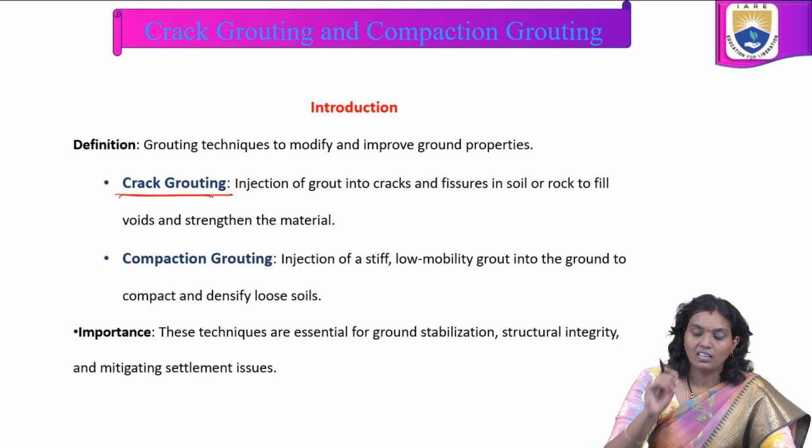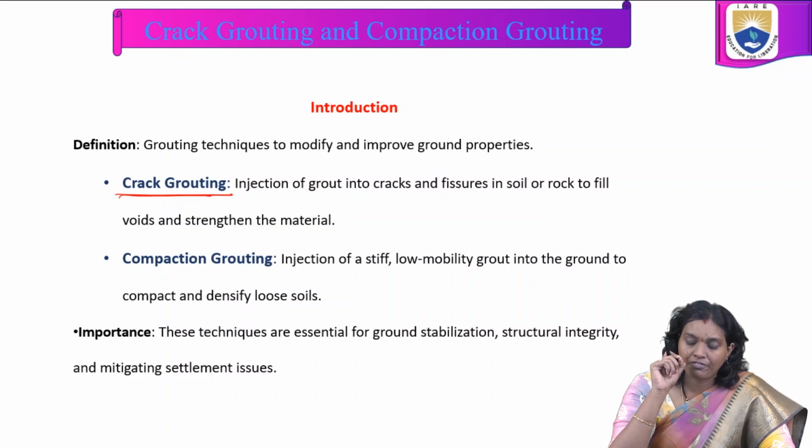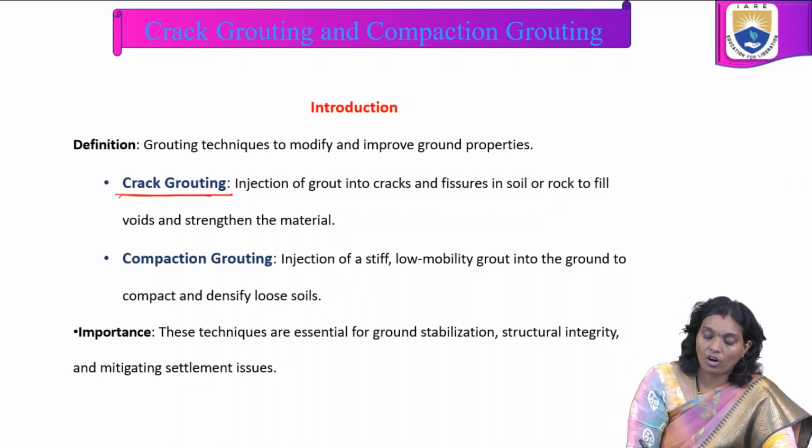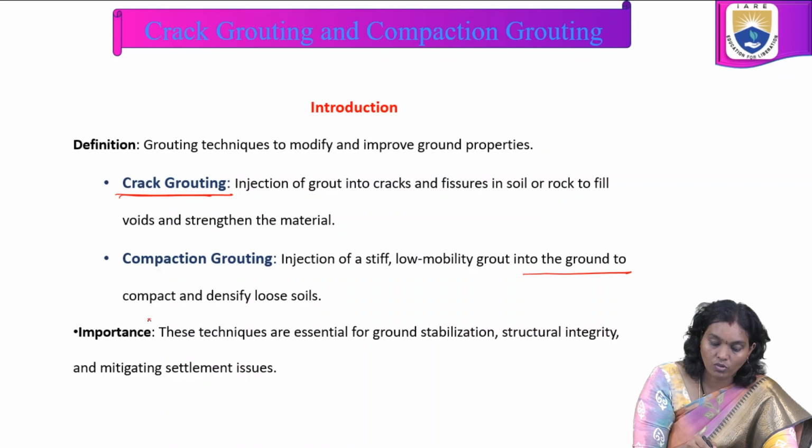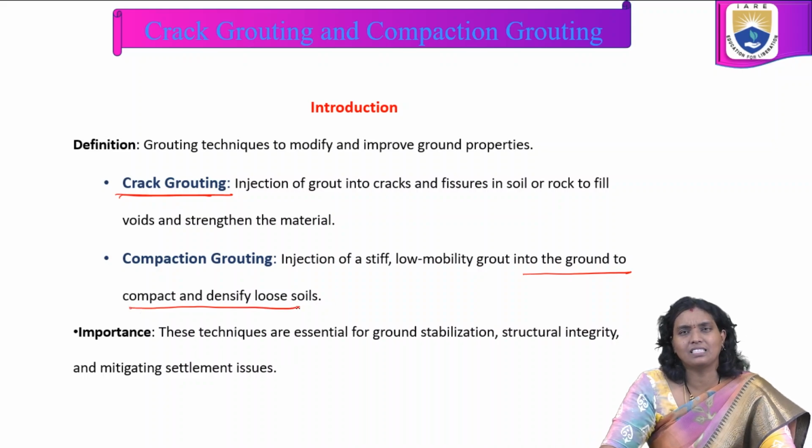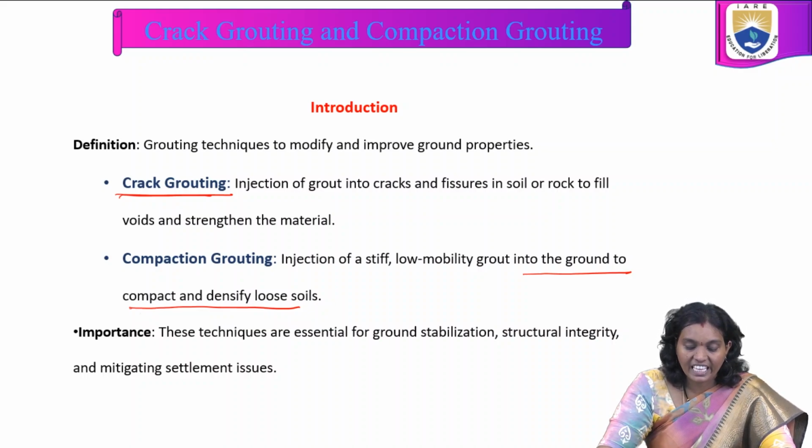And the injection of stiff, low mobility grout into the ground to compact and densify loose soils is known as compaction grouting. These techniques are essential for good ground stabilization, structural integrity and mitigating settlement issues.